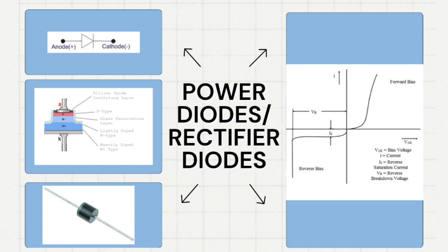created. A power diode can withstand high reverse voltage under reverse bias because of its enormous current capacity and resistive structure. A power diode's reverse current, including reverse saturation current, is measured in hundreds of milliamperes. Some of the applications of rectifier diodes are half-wave rectifier, full-wave rectifier, battery charging circuits, inverter circuits, flywheel diodes, DC power supply, and SMPS.